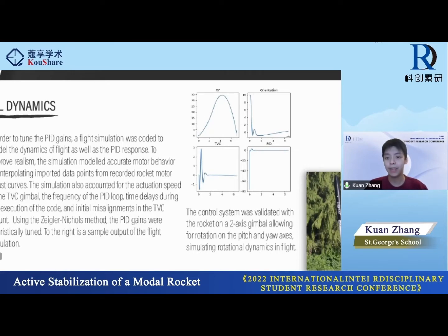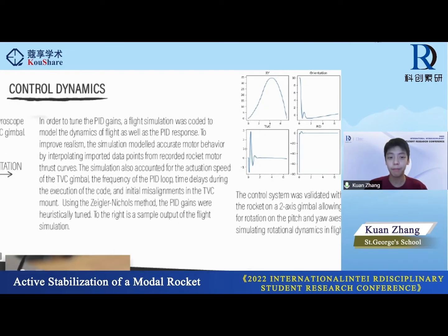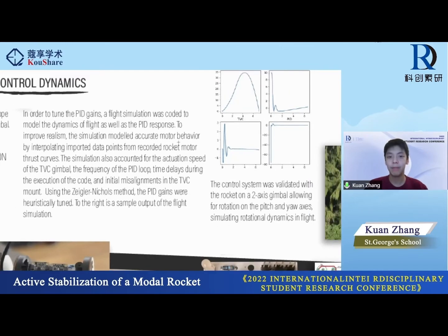This is the orientation plotted over time, the TVC output's direction plotted over time, and this is the response from the PID algorithm. To improve realism, the simulation modeled accurate motor behavior by interpolating imported data points from recorded rocket motor thrust curves, which are available online.